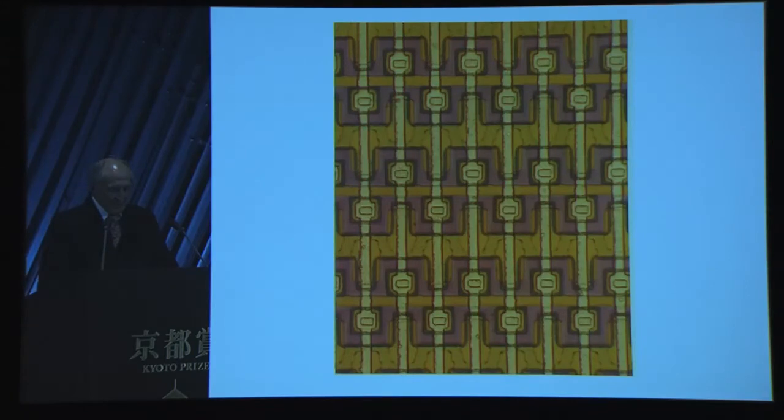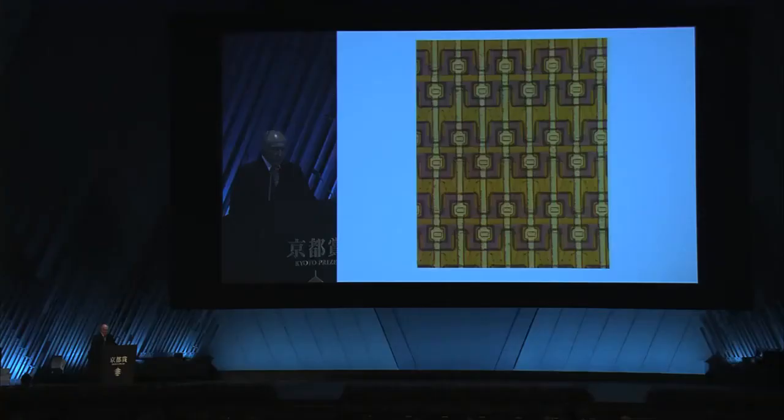This slide shows a greatly magnified photograph of some memory cells in that chip. The light-colored vertical shapes are the aluminum word lines. They're connected to small square features, which are the transistor gates. The horizontal shapes are the bit lines and the top electrodes of the capacitors. Next slide.